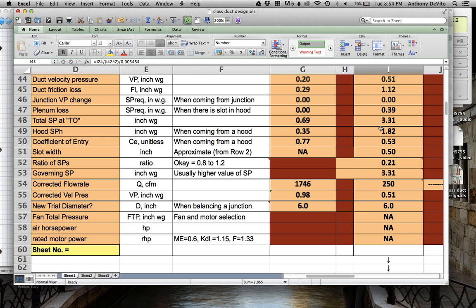They need a drastically different amount of static, 0.69 and 3 inches. That's drastically different static pressures at C. So you've got to choose one or the other. They're so far apart that we want them to be no more than 20% off from each other, right? So that we don't get weird system effects there.